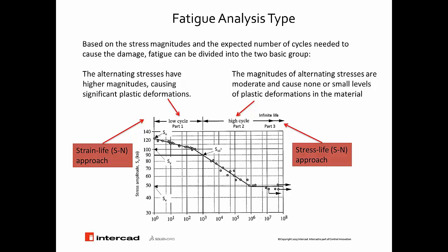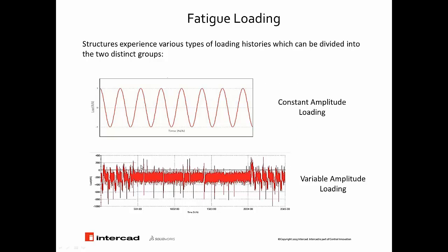But the main highlight is that in SolidWorks Simulation we are able to simulate high cycle fatigue, where the level of stress is near the failure limit or even less than this. There is no significant plastic deformation on the structure. What we are really concerned with is what happens if these stress levels are repeated again and again, and what the outcome of the study is. All right, now as we know, we're talking about fatigue, and it is directly connected to the loading, a load which is getting repeated.